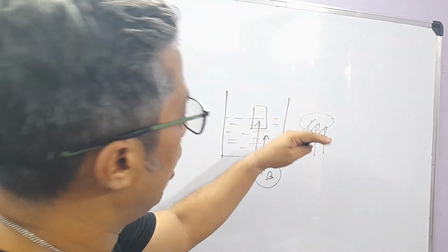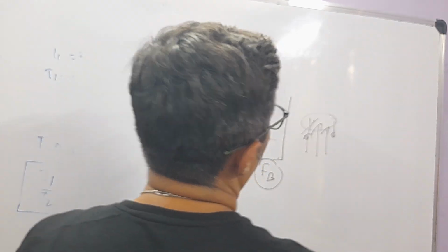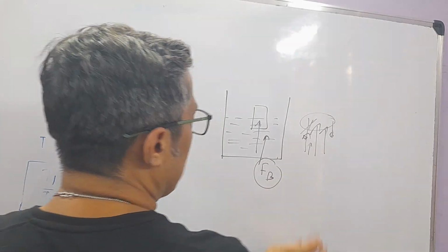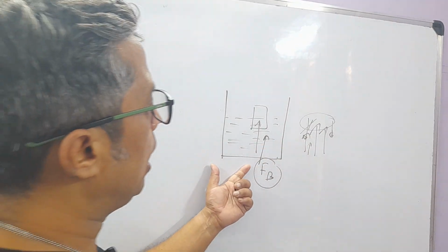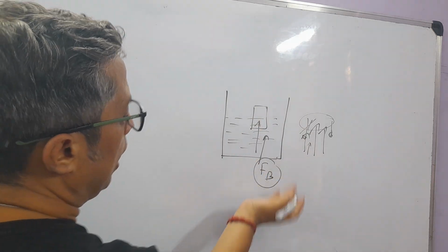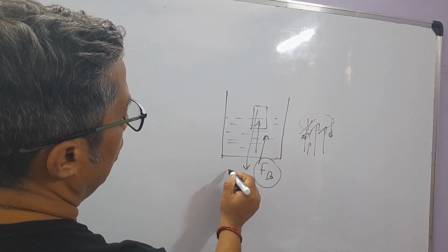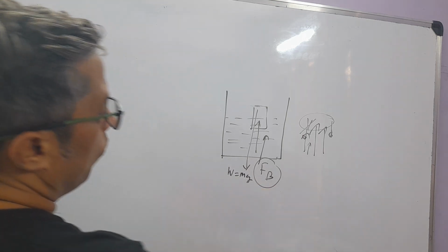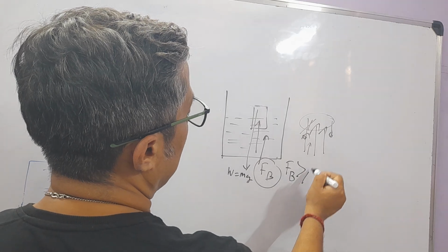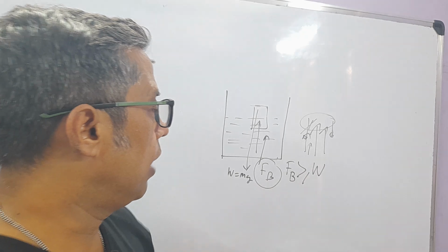Whenever we are descending, it is in a very controlled manner by increasing the area of the parachute, right? So this upthrust force is valid for liquids and also for the gas state. Here we are interested in the liquid part. For liquid, we get an upward force, and this object will receive a downward force. Now, what is the condition of floating? The upward force must be greater than or equal to the downward force. If this condition is satisfied, then only the object will float.